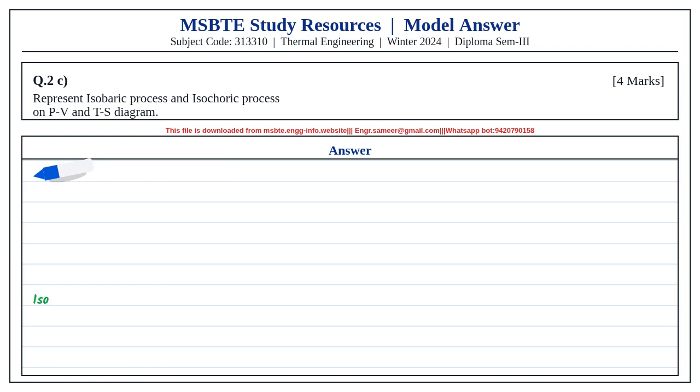Question 4E. Determine whether the steam is wet or superheated and calculate the required value. Given pressure is 9 bar and specific volume is 0.30 meter cube per kilogram. From steam table at 9 bar, saturation temperature is 175.4 degrees Celsius and specific volume of dry saturated steam is 0.215 meter cube per kilogram.